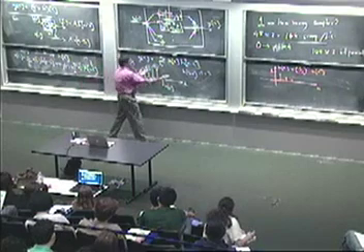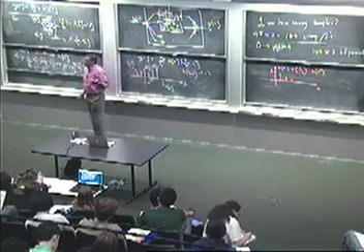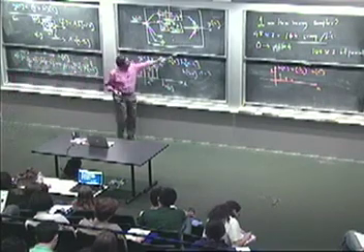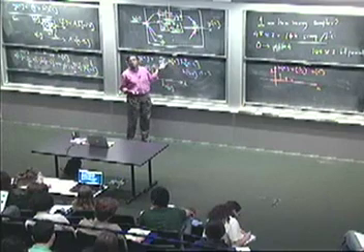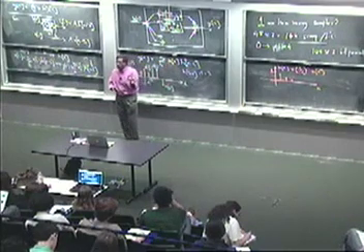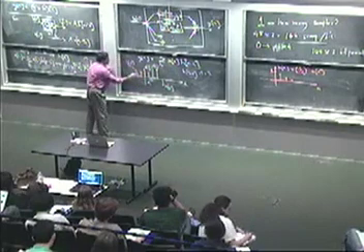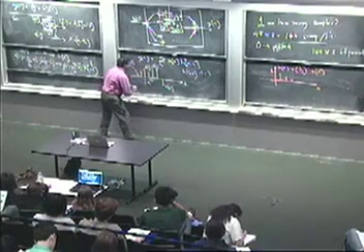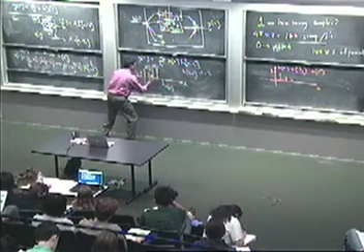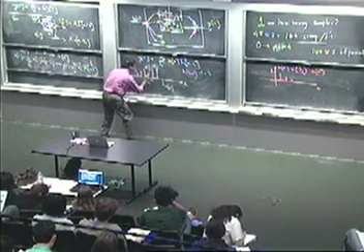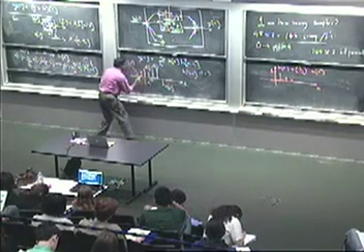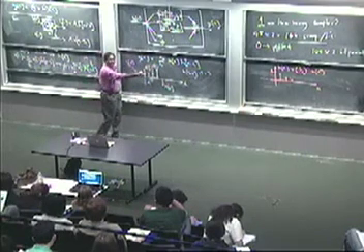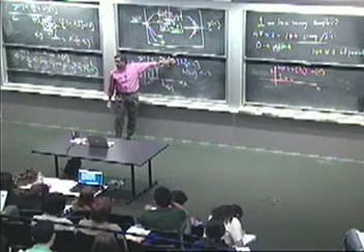So now on a single figure, you've managed to plot these two. What's the remaining operation? What you've got to do is the point-by-point product of these two waveforms and sum over the entire time axis. It's like taking a dot product, right? So you're going to take this value of the red curve. Well, actually, let me slide it over. Let's do this case. This is the slid over case, right? You're going to take every one of the purple values multiplied by the white and sum over the entire time axis. That's an implementation of this.